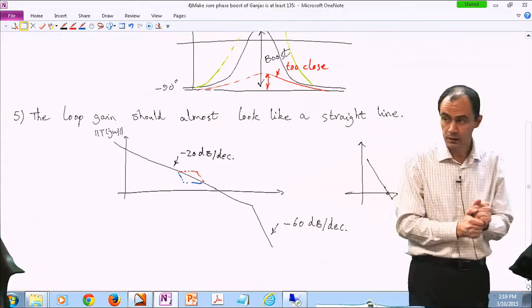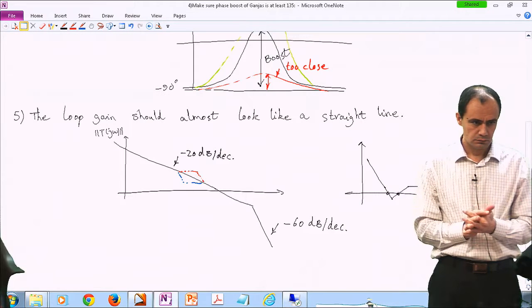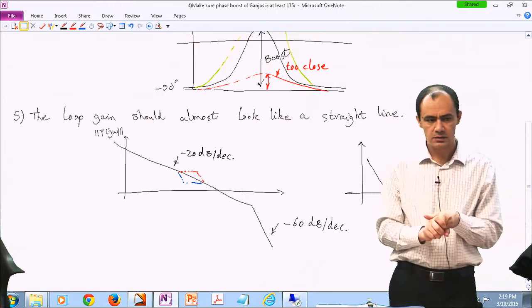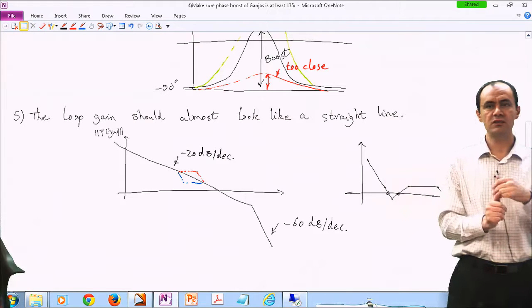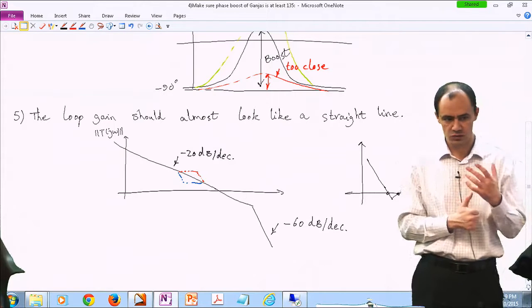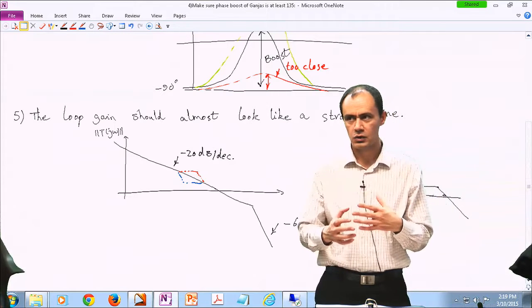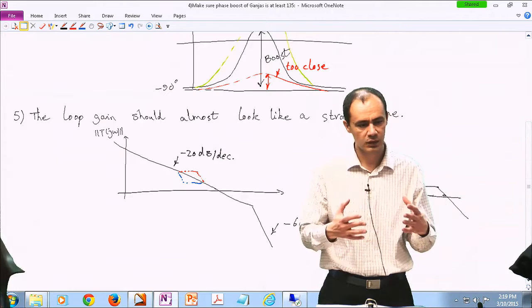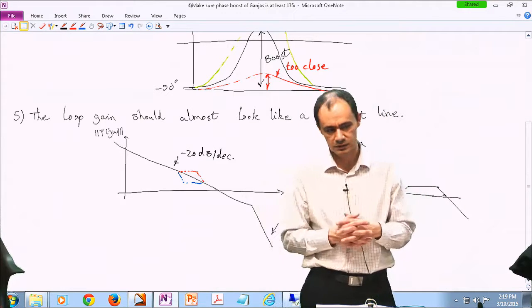Okay? So boost is actually stabilizing the converter at the frequencies at which it is operating, right? What is the stabilizing? The boost that is being provided. Oh, the boost, yeah. The boost is giving you extra phase margin, so it makes your system more stable. So you always are trading off between stability and bandwidth. If you have more phase margin, that means you can actually increase your bandwidth.